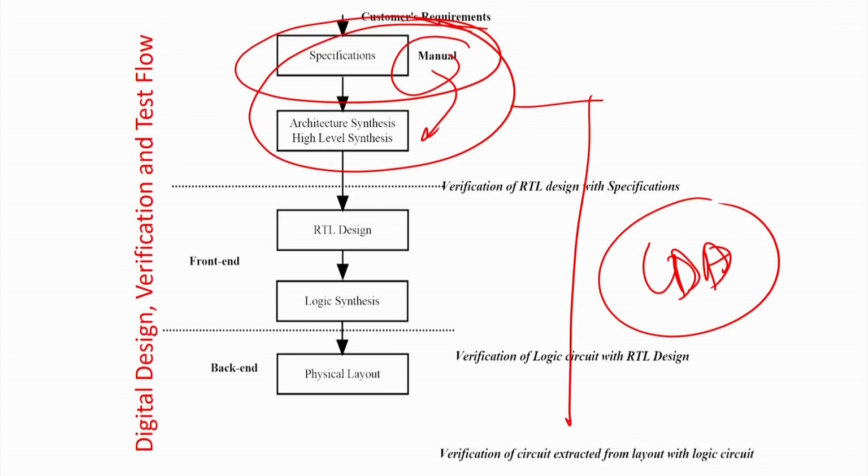The difference between a heuristic and an exact algorithm like Quine-McCluskey or the Karnaugh map is that you will always get the minimum size circuit or minimal implementation. But in the case of Espresso, you will get minimal or slightly near the minimum value, but the speed of implementation is extremely fast. Like if I give you a 100 variable function, the Karnaugh map cannot solve it. Quine-McCluskey will take years to do it because it is an exponential algorithm, but Espresso will solve it in a click, because it is a heuristic. It is very interesting, and we will also cover it in this course.